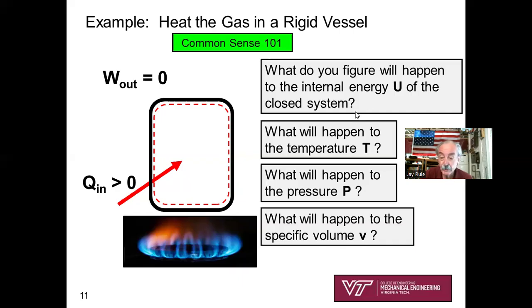Okay. So quick answers. What's going to happen to the internal energy? Increase. Temperature? Increase. Pressure? Increase. Specific volume? Stay the same.